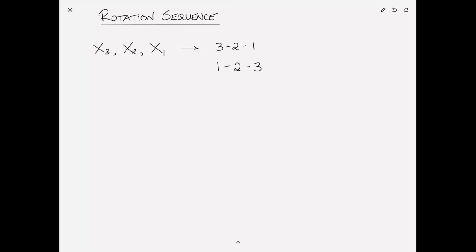It turns out you actually don't need to rotate about 3 different axes. For example, I could have rotated in a 2-1-2 sequence. So rotate about the x2 axis, then about the x1 prime axis, and then about the x2 double prime axis. I don't have to use 1, 2, and 3 in my sequence. And it turns out that any of these sequences, with the correct angles, can rotate me from any given orientation into any other orientation. But here's the thing.